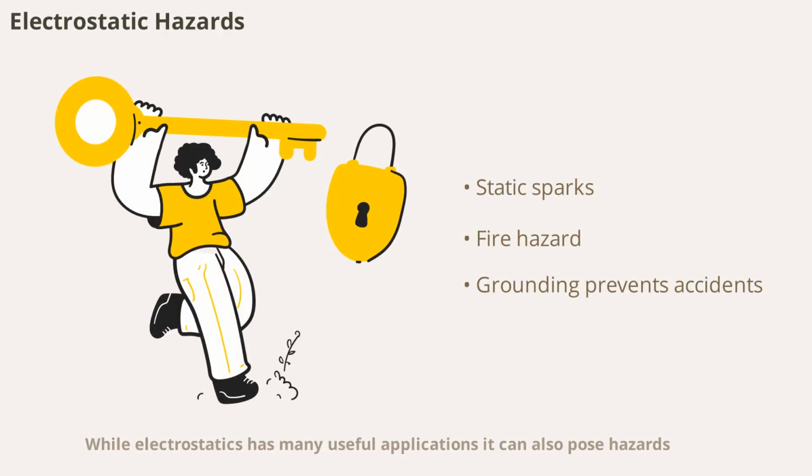While electrostatics has many useful applications, it can also pose hazards. Accumulated static charge can cause sparks, leading to fires or explosions in sensitive environments. Proper grounding and shielding are essential for preventing accidents in industries that handle flammable materials.